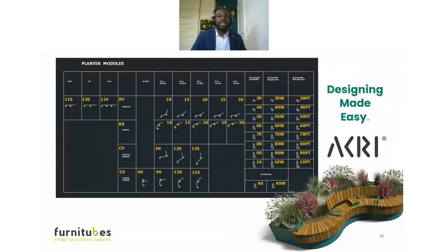We like to make designing these easy, and this means we can supply CAD blocks, which makes it really easy to plot these panels onto your GAs. It's really important to engage with us because we are the steel fabricators and we know what the constraints are. Say, for example, if a panel is anything less than 45 degrees angle in a corner, that could form a problem in terms of being able to secure supports on both sides of the corner.